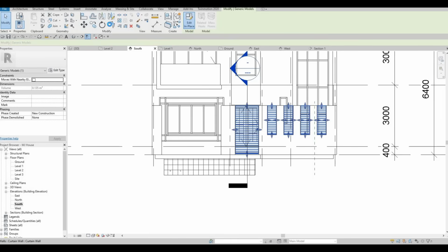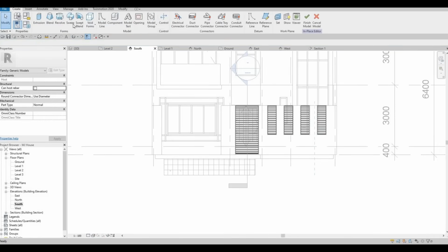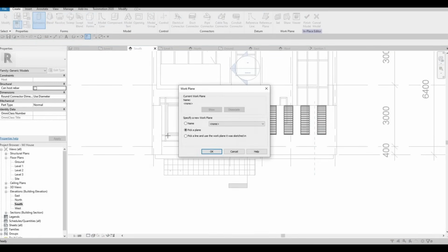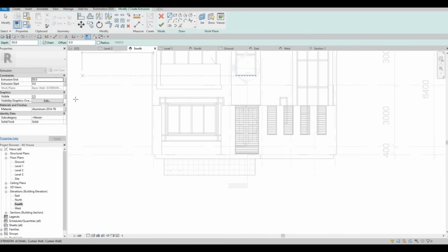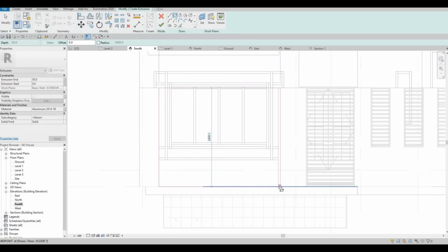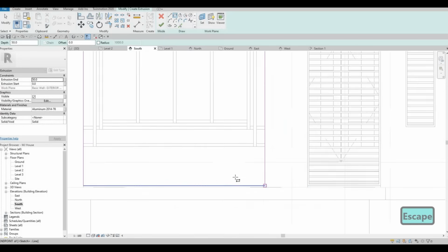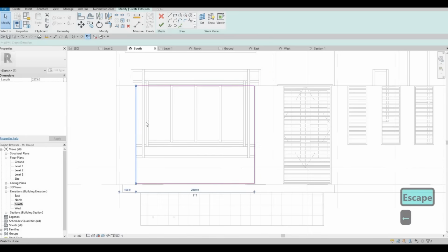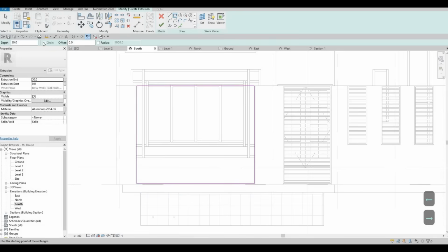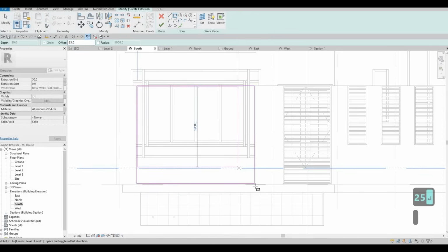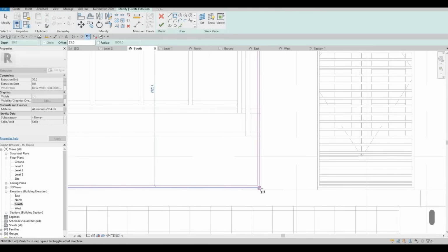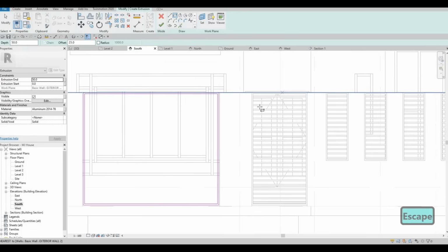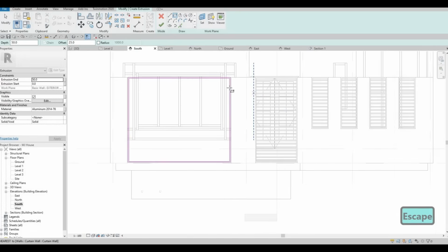So edit that and then create an extrusion, pick a plane, remember to choose this, and then create a case and then give it some space at the top there, move it a little bit, and then here offset to 25, space bar to go from the inside to the outside or outside to inside.